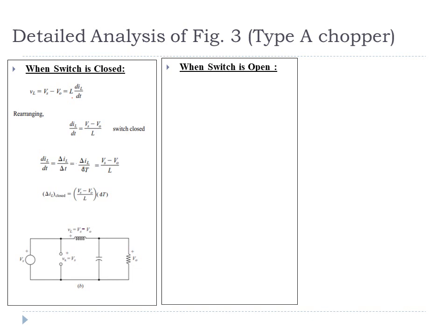When the switch is open, the circuit becomes like this. Since the current will still flow through the inductor, the path will be provided through the diode, and Vs becomes 0. So the inductor voltage drop is equal to minus V naught. So VL equals minus V naught, which can further be written as L dIL upon dt.